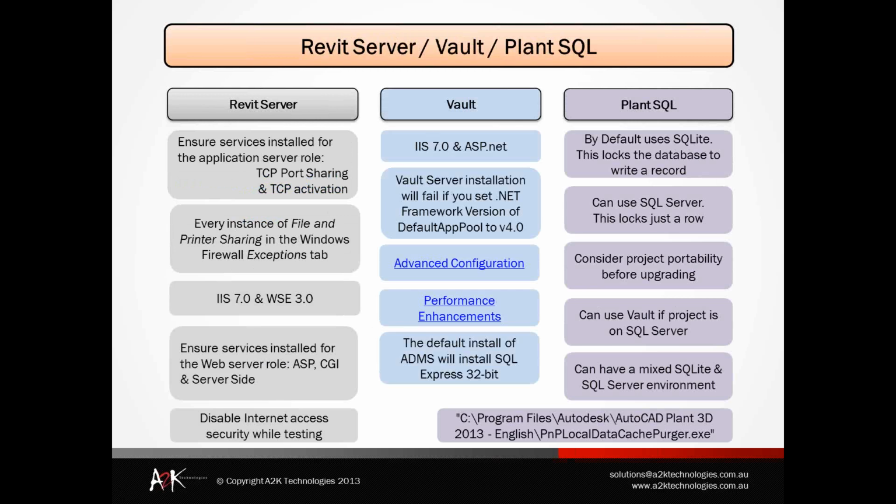there are the issues with Revit Server. The best advice we can give with Revit Server is that most of the instances we see relate to not having checked off all the installation requirements, etc. The prerequisites are all available on the Autodesk wiki help for Revit, and a quick Google search of Revit Server installation should reveal the wiki help website.